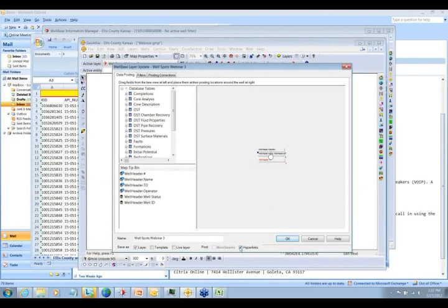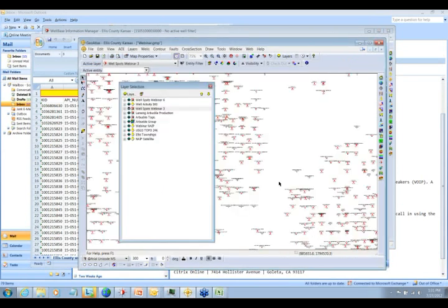You will notice that we have a new checkbox in Well-Based Layer Create. Well-Based Layer Create, for those of you that aren't familiar with GeoGraphix, is where all the layers are created that you want to see on your map. All the well layers that you are going to visualize on your map. If you want to add those hyperlinks, you can just check the hyperlink button here, create the layer, and we'll just quickly zoom in.